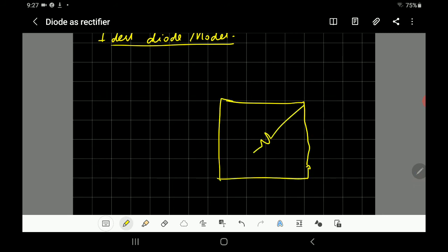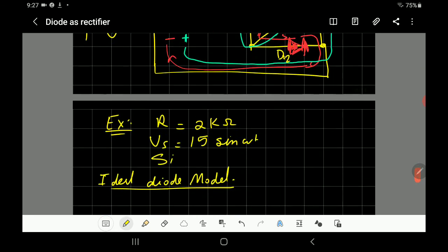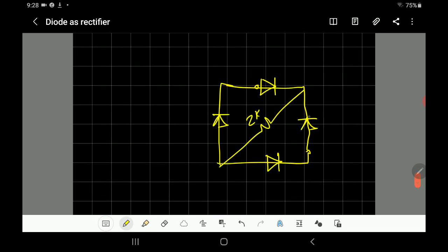And this is the resistance, 2 kilo ohm. They are conducting, the one here. Let me put it in this way, and the other one in this direction. So this will be off, and this will be on. This will be on, and the other one will be off. I need to find the voltage for any one of those, but I will erase the off ones because off will be like an open circuit. But of course, this is conducting, and this is the supply.